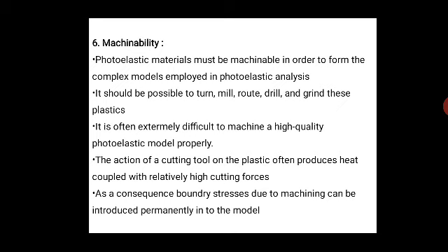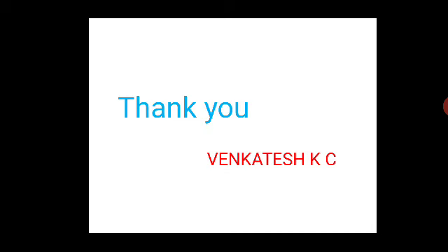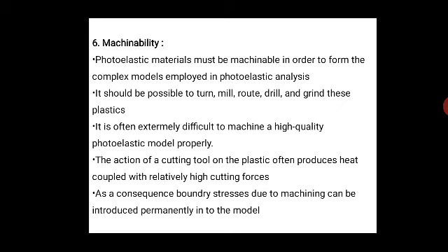The photoelastic model is mounted to a metal template which describes the exact shape of the final model. The template is guided by an oversized diameter pin, which is coaxial with the rotary file, and the rate of feed along the boundary of the model is carefully controlled.